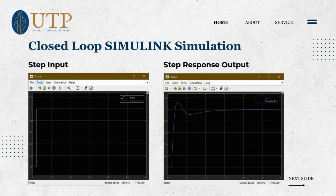In this part of the simulation, we apply a step input to mimic a sudden seismic shock, and the graph here shows the step response output. This step response indicates how quickly and smoothly the system can return to a stable state after a seismic disturbance. A well-designed seismic isolation system should have a controlled, non-oscillatory response with minimal vibration after the initial shocks, as seen here.